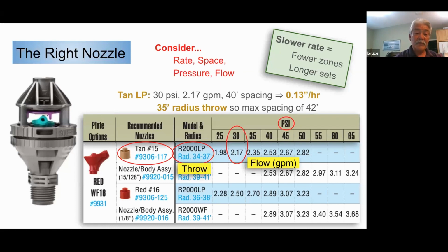So we want to hit it with some sprinkler heads. So you want to come up with something that's a factor of the 8 feet, so that we're in that row. So let's say on every 5th row, we would have it at 40 feet, would be our spacing on that. If it was every 4th row, you would be at 32 feet. So we want to look at it. For our client's sake, we want to have the best product for the job without going overboard,